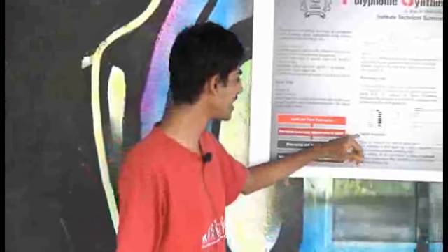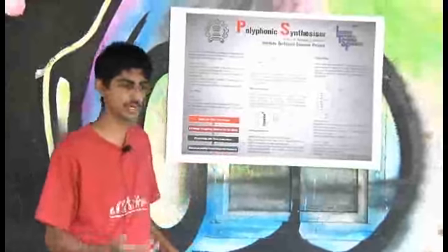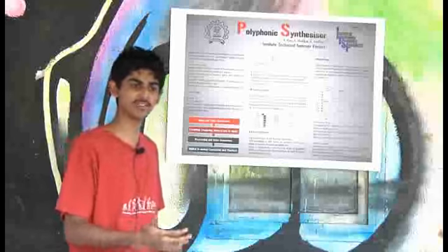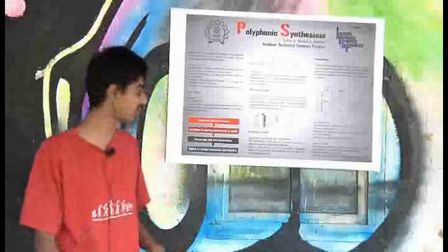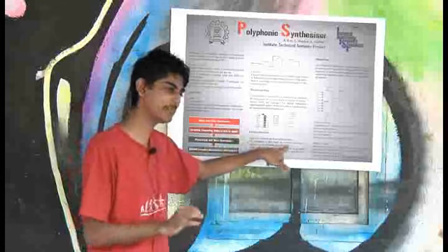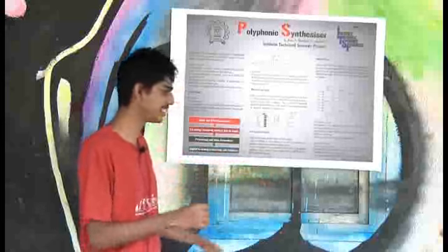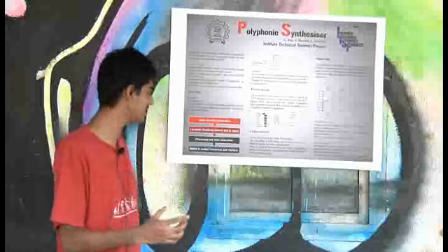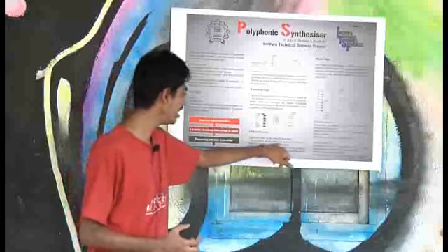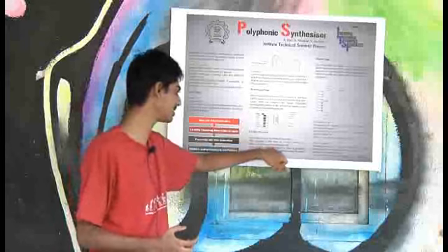So the next thing is, how have we sampled the sound? What steps have we taken to ensure that the sampling of the sound is done at a very accurate rate? The sampling rate has to be very accurate, otherwise the frequencies will be distorted. So that we have done using another concept known as a timed interrupt. A timed interrupt in the Arduino microcontroller is something that is set off at a periodic interval which can be set. This directly decides the sampling frequency, and this gives the sampling rate. The inverse of the sampling frequency gives us the sampling period.